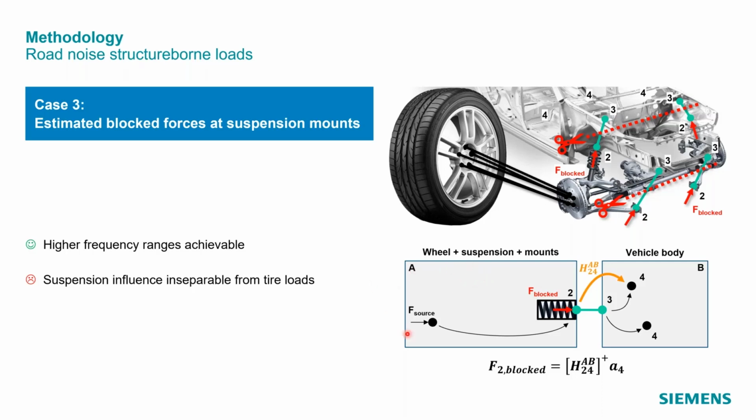with the EDU, is we simply increase the scale of our source components. So instead of defining the interface between the wheel and the wheel hub, we can also take the wheels and the suspension system together as a single component and simply cut that component from the rest of the body at the interfaces between the suspension system and the body. So this will make life easier in a way, because we can again apply in situ TPA here on the passive side of our mounts.